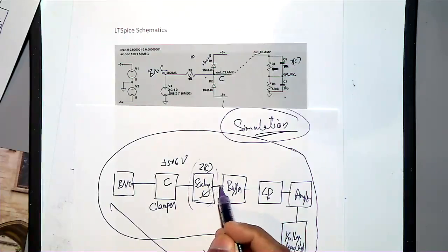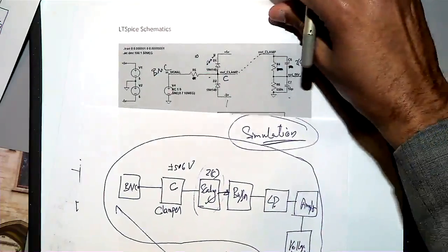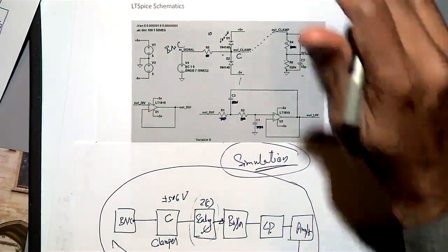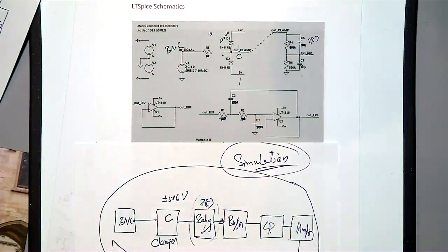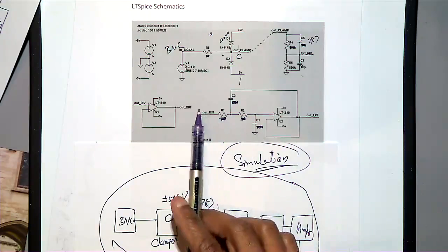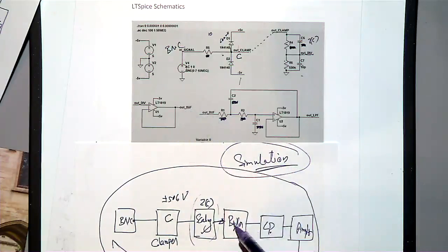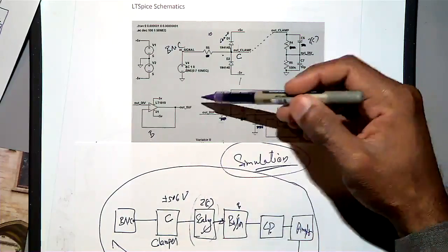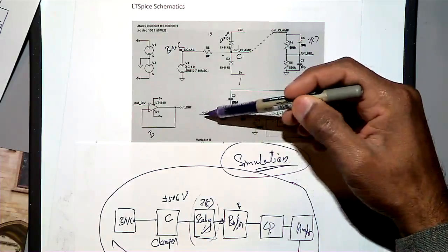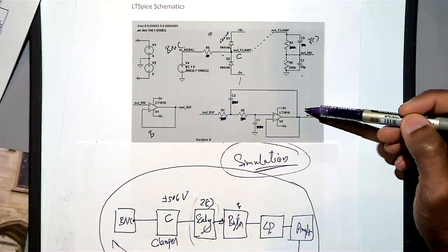After that you are going to a buffer, so here we got a buffer circuit. See, here we just use it as a buffer in this design. And then the buffer output we are going to see from the buffer. So that is a buffer, B. From the buffer, it is going to the second order. This is a second order filter.